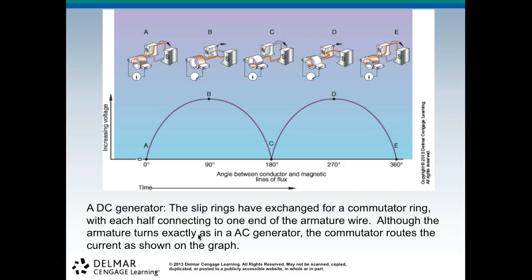The sine wave does not drop, it stays positive. Compared to our last one, where it came down and around and then dropped below before meeting back at 360, here with this new commutator ring we start parallel at 0, go to 90 degrees, which is peak, and then back down to 0 at 180, coming back up at 270, and then 360.